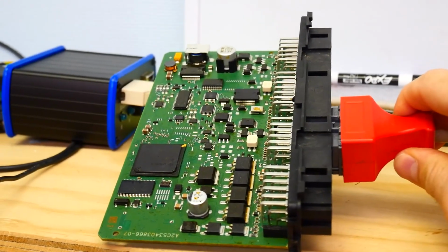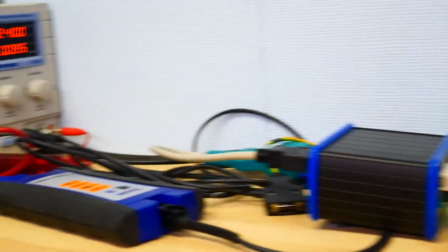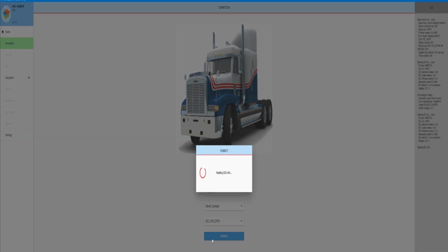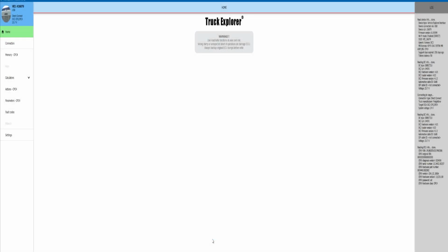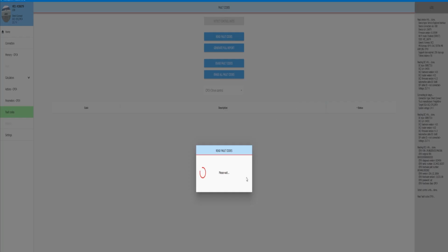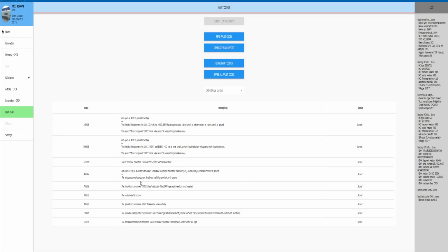We've connected our CPC4 back into our bench testing system. We'll go ahead and connect, and we're getting the correct power draw. Now this one is the one that was connecting originally, but we had an active fault. So let's see if that hardware fault is still active. We did leave the CPC4 plenty of time to cool down so that we would not get a false positive. And it looks like our powertrain controller hardware fault is stored.